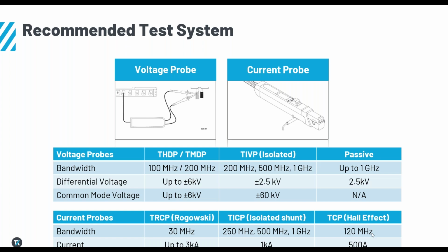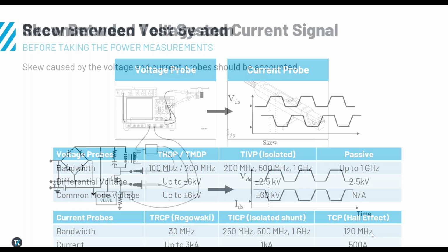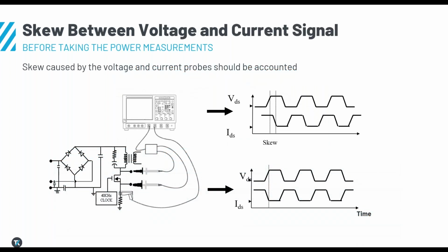Our website has all the options here, and we'd be happy to help you understand which one is best for your measurement system. For the deskew, we have that signal source, which I referenced, and then there's also a fixture. This fixture is great because you can hook up multiple probes to it, so the signal arrives at the same time per channel. There's actually a procedure within the scope that can take care of this for you, or you can do it yourself manually.